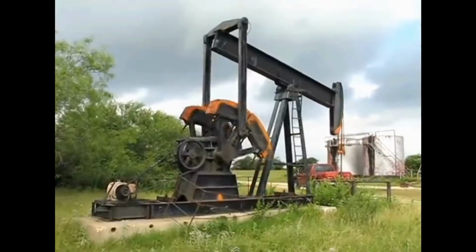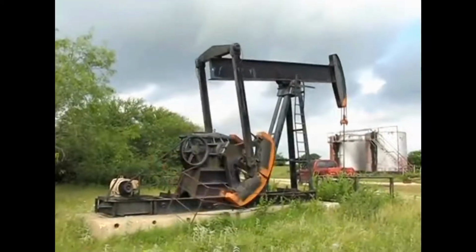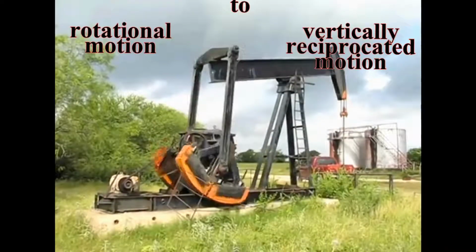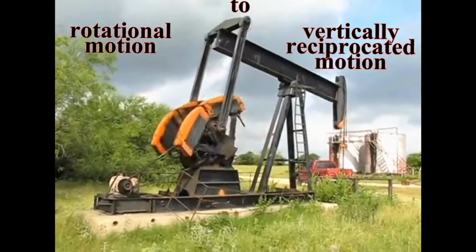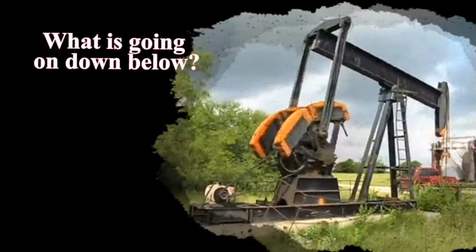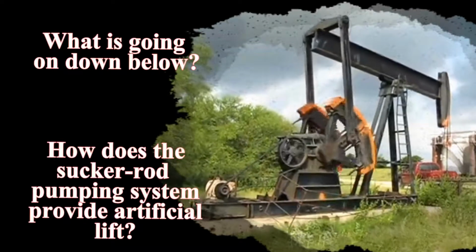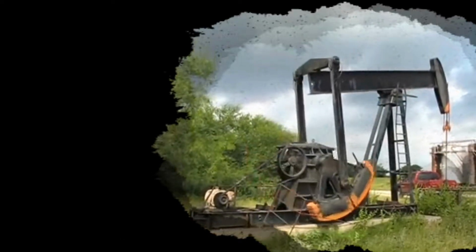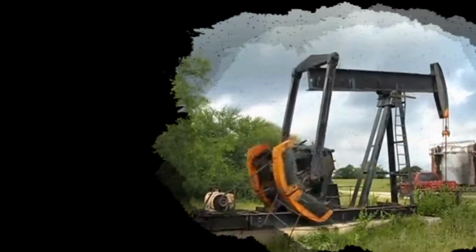So far, we have been looking at what is visible above the surface. From this perspective, basically all we can see is a device that converts rotational power into a vertically reciprocated motion. This means that the sucker rods attached to the horse head move up and down, but what is going on down below? How does the sucker rod pumping system provide artificial lift? To answer these questions, we need to follow the sucker rods down into the hole into the subsurface.